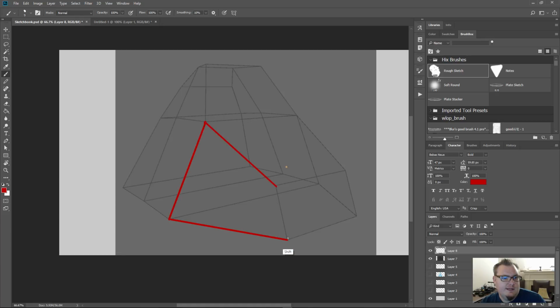And then this right here is the first full face that we have. Here's the front section, that's going to be another face. Another section, it's going to be another face. Now everything behind these we know is going to be hidden because these are already in the way, so you're not going to be able to see any of these lines back here.